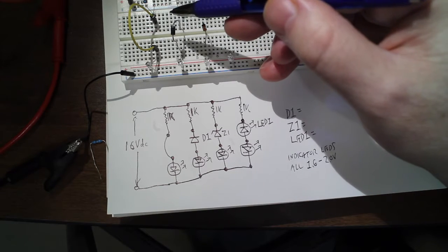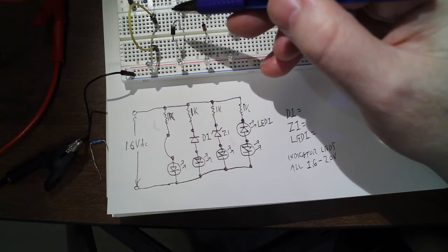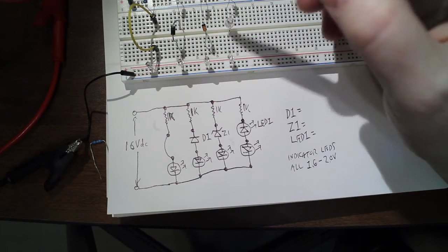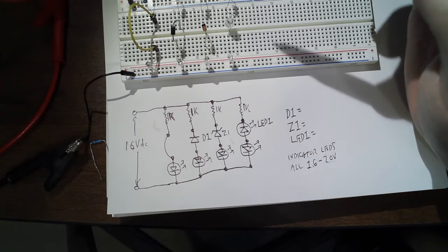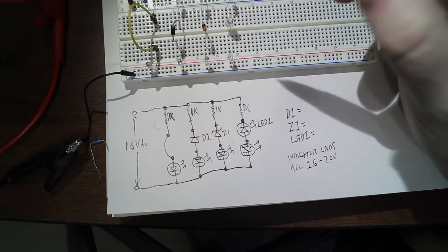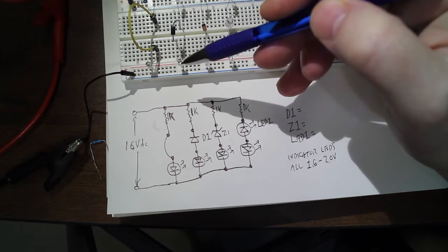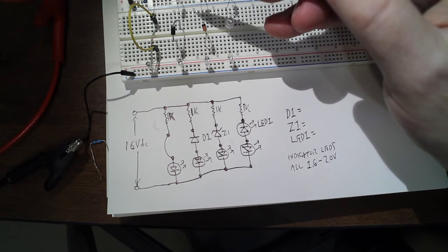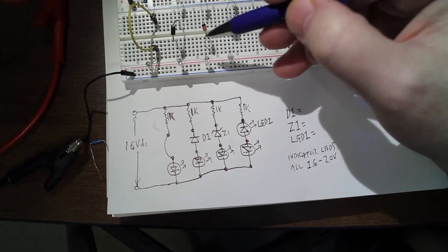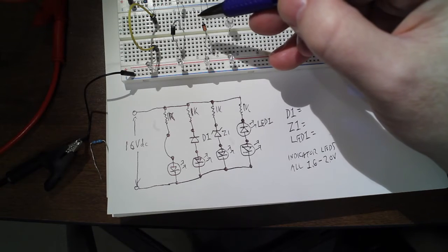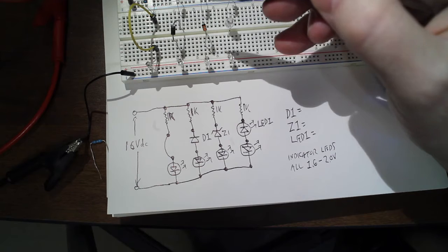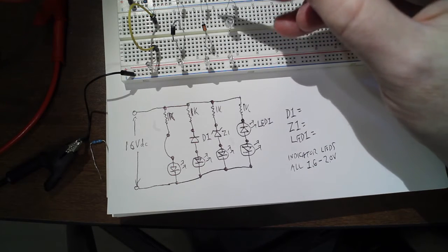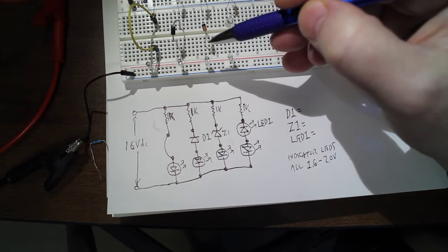This is why the 1N4000 series has a 1N4001 that has a peak inverse voltage of 50 volts. It has a 4002 that can handle 100 volts, and it goes all the way up to a 1N4007 that is designed to handle a reverse voltage of 1000 volts. Totally depends on your application. Zener diodes also come in different voltages, but they're not peak inverse voltages, they're called Zener voltages, and they are designed to conduct at that voltage.